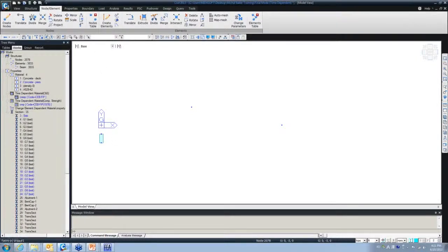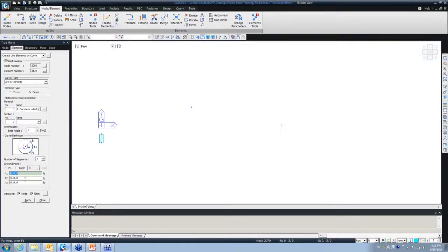Okay, so I can go to the create lines on the elements, and 3 points will be this point, that point, and this point. And by default, it created so many of them because I'm using this on the other elements. So anyway, you can simply create those. These are intersecting with everything else.